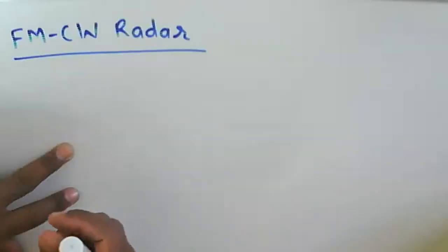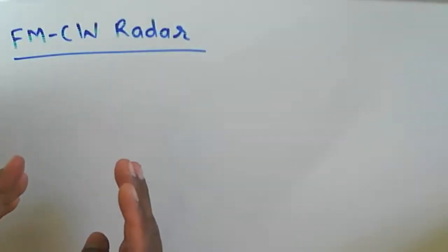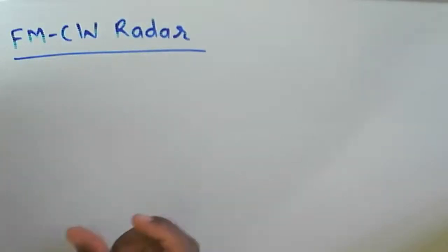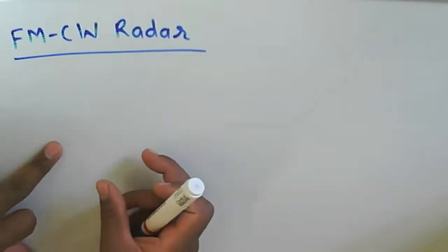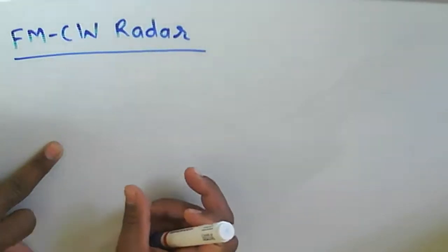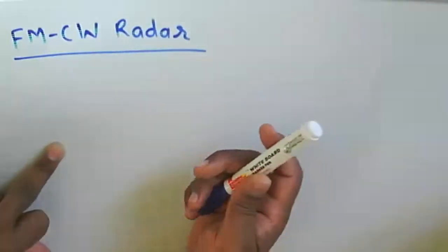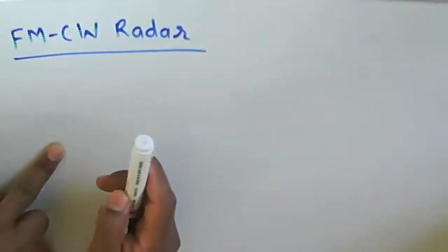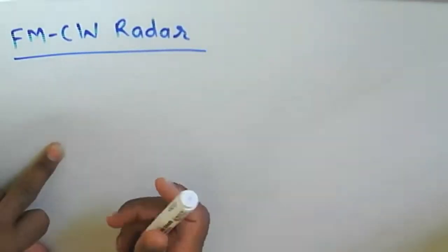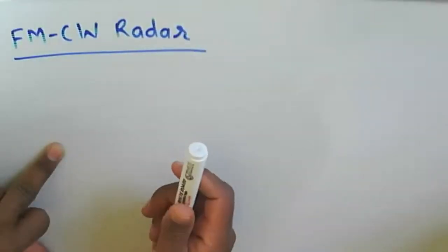Then, one more issue is that because of a narrow bandwidth, we have limitations regarding the spectrum, and we need to work within a particular spectrum. If we increase the spectrum to a broader one, there will be a limitation at the receiver, and there will be an issue with the signal to noise ratio at the receiver.